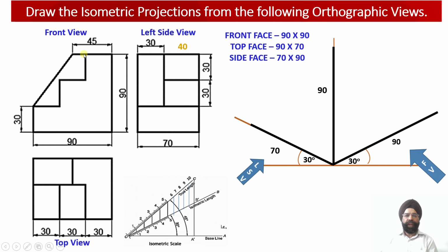So you move 45 millimeters towards the front face. So this is the front face of the solid, and then this web, which happens to be 30 millimeter thick or 30 millimeter wide, will be moving down to this point, which is the top point of step number 3 over here. And then there are 3 steps, as we have discussed.